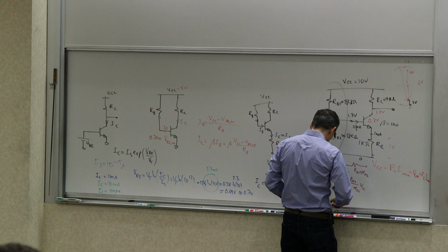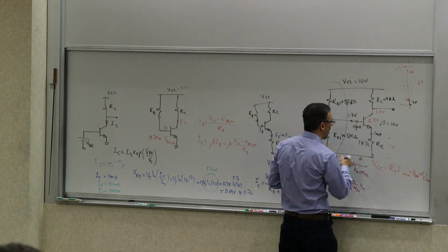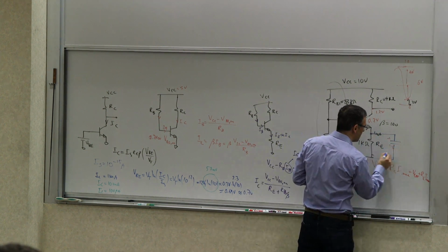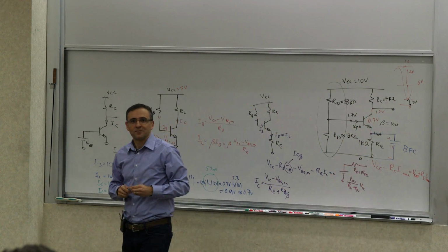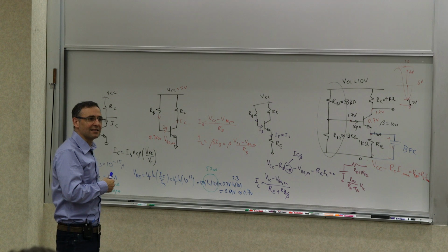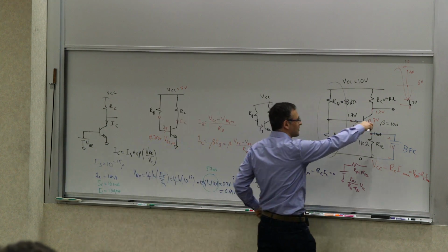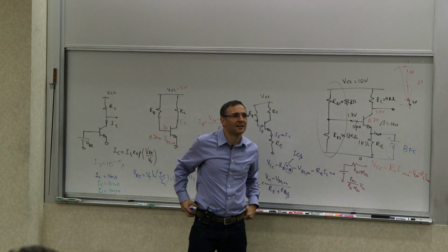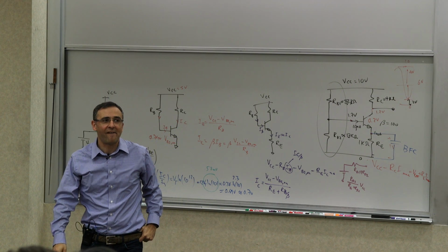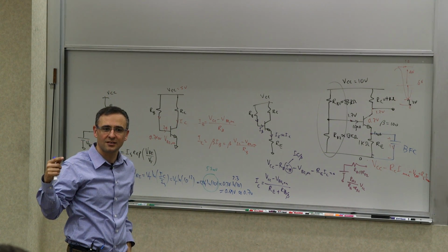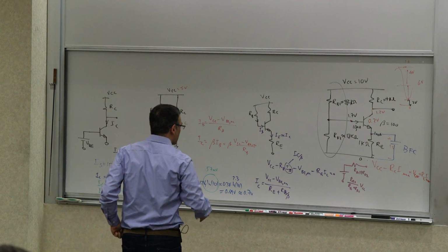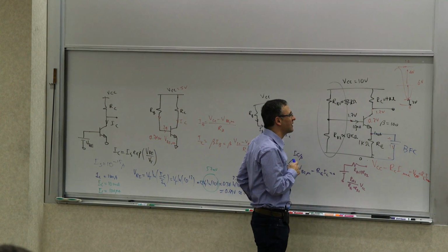So one of the things you could do, you can say, look, I'm going to put a big fat capacitor here and just basically bypass that. Just create a short. So at AC, you basically create a short. At anything that changes, you connect it to ground. So from an AC perspective, what is the gain now?